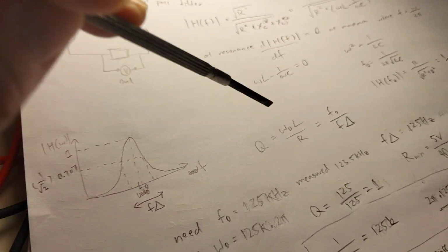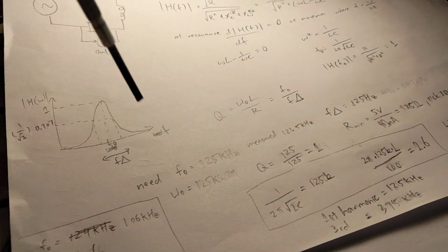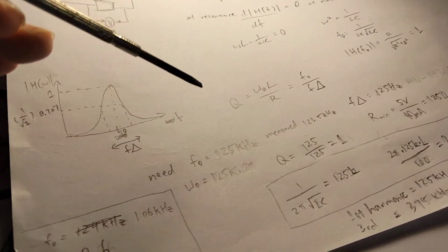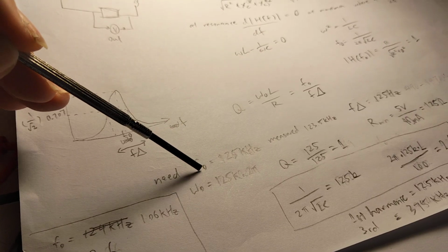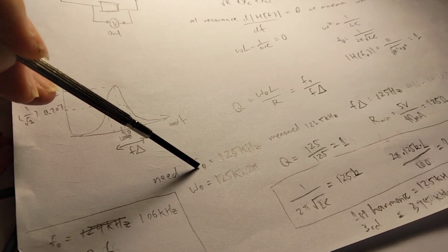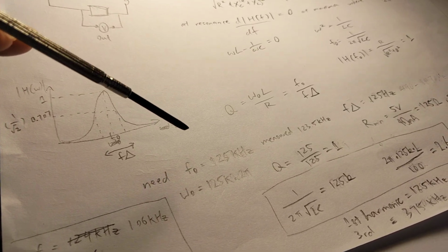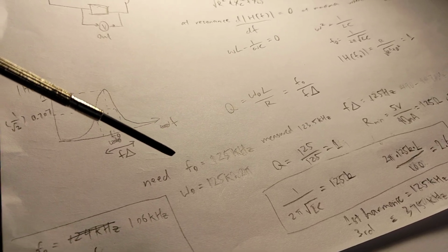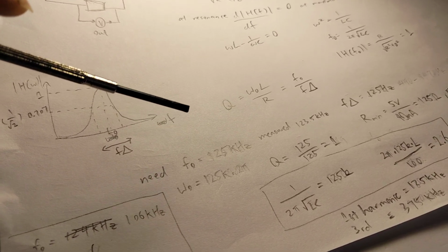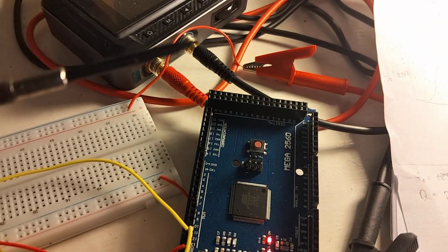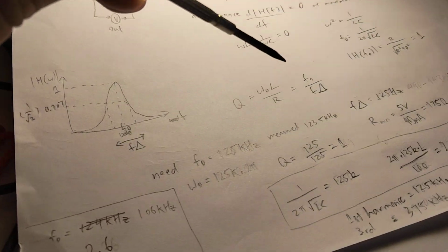So now there's a Q factor, and for me, at first I wanted to just use the Arduino's output PWM pins' native analog signal frequency, which on my Arduino Mega 2560 has a maximum of 980 hertz.